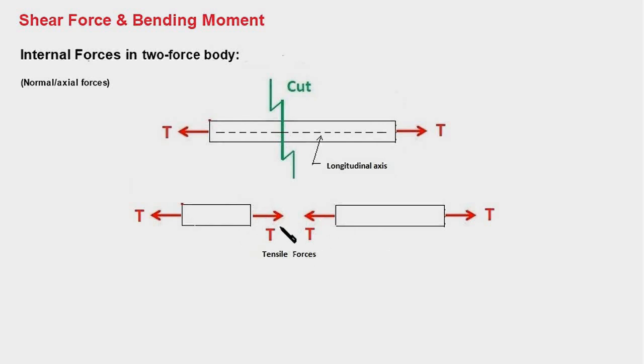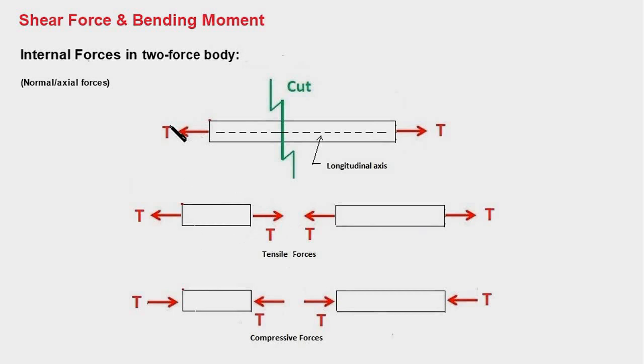And in this particular case, when the external forces are directed away from the body, the internal forces also are directed away from the body, and therefore they are called tensile forces because they are stretching the part on which they are acting. And if the external forces on the body are just in the opposite direction,